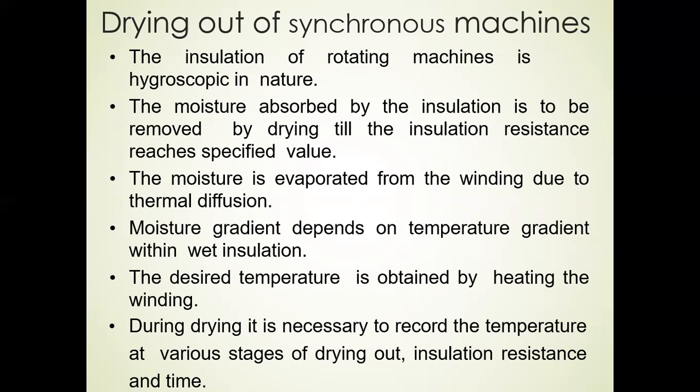To measure insulation resistance of windings rated up to 1000 volt, a Megger of 500 volt is used, while a 1000 volt Megger is used for machine winding rated 1000 volt and above. The phase-to-phase and phase-to-earth insulation resistance IR at the working temperature of the machine should not be lower than the value found from the analysis. That is already derived for that particular machine.